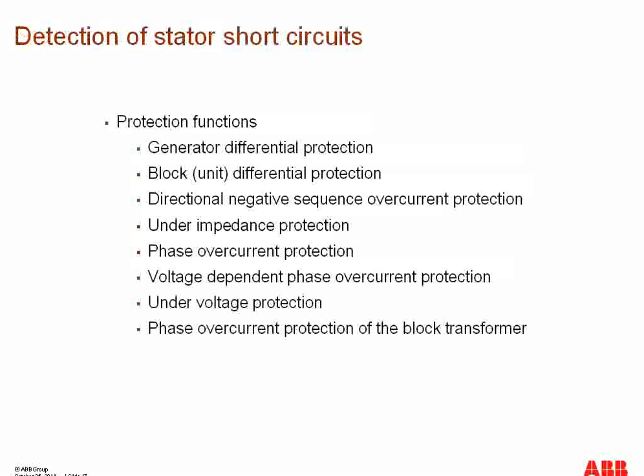In addition to differential protection, we can have directional negative sequence overcurrent protection as well, and we can have impedance protection, phase overcurrent protection, and other types of protections as well, like voltage dependent phase overcurrent and phase overcurrent protection of the block transformer. So there are several ways to detect and eliminate the stator short circuits.